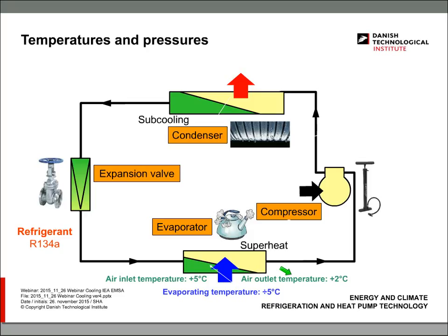And the refrigerant inside the evaporator, when it changes from liquid to gas, has to be heated up a little bit more so that we are sure that it's gas that enters the compressor. If we get liquid from the evaporator to the compressor, we damage the compressor. We call it liquid hammer, and it's not very healthy for the compressor.